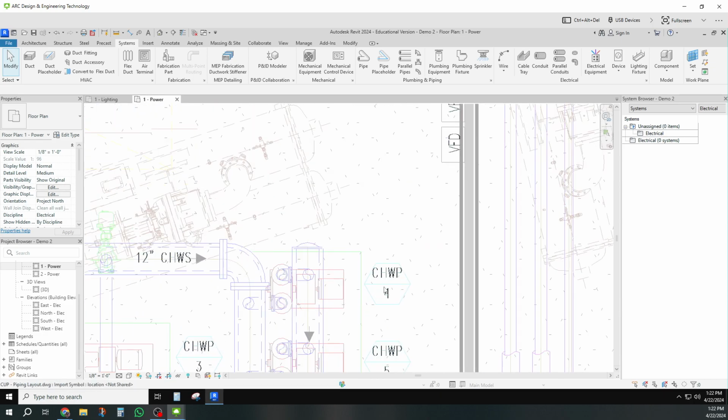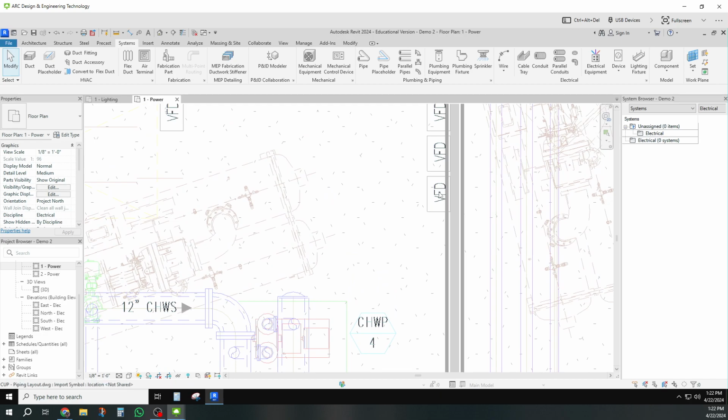Okay, and so each pump has a name. They've got these things called VFD on the wall, variable frequency drives. It's a little bit older style of doing things. Now variable frequency drives are much more integrated into the motor control package and are more likely to be right on the pump stand, the pump base. So we're just going to put a junction box right here and just put a big panel in the wall. Now these types of pumps are usually in the range of, say, 2 to 10 horsepower.